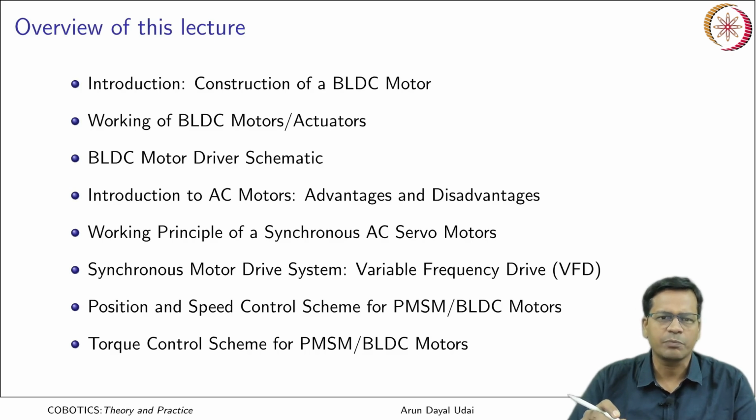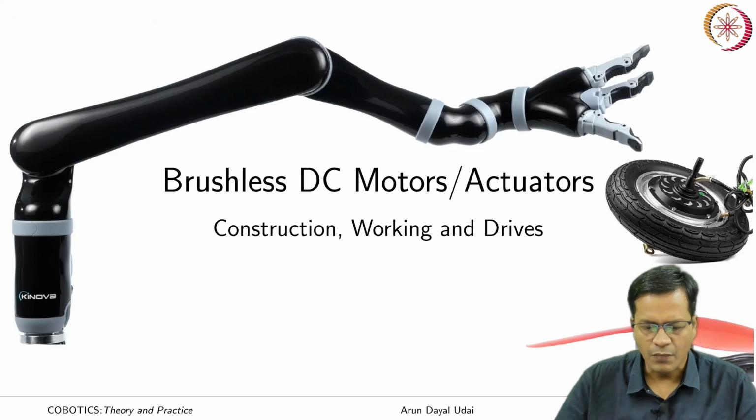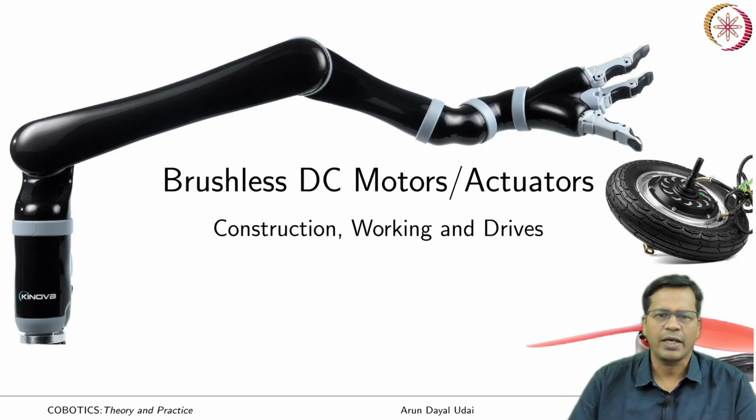We'll see the working principle of a synchronous AC servo motor, synchronous motor drive systems, that is variable frequency drive. We'll discuss the position speed control scheme for PMSM or BLDC motors, and the torque control scheme for PMSM and BLDC motors.